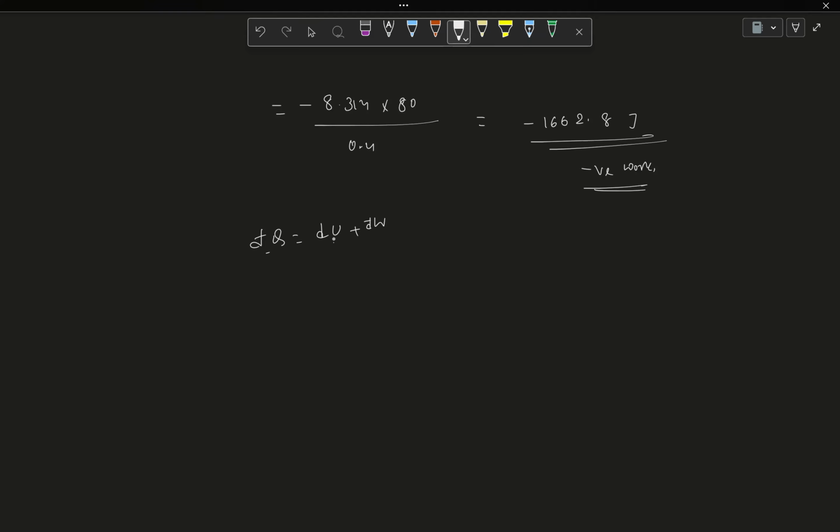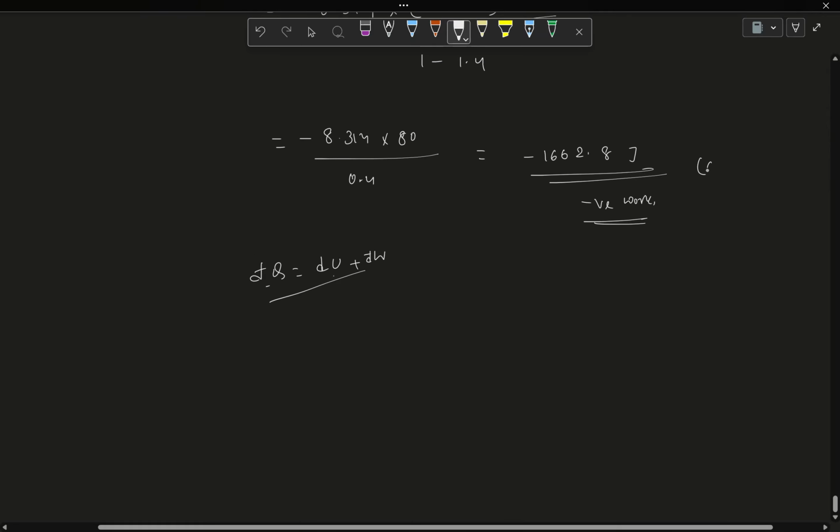But in this case it is a generalized polytropic process, nothing mentioned about heat not being exchanged or anything, but just for the idea I was saying that the work done can be negative in this case. We do not need to give any explanation for this minus sign here, because this is not what we have been asked in the question, but I was giving an example for the context only. Okay, so this is our answer, and you can match the option.